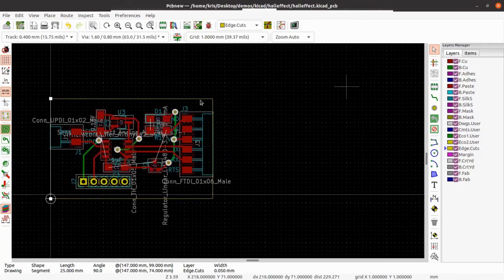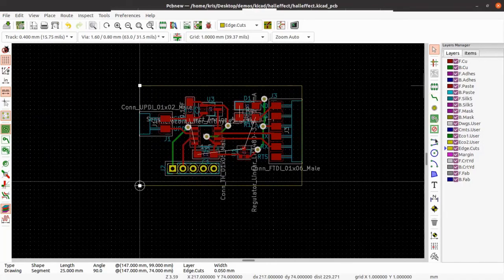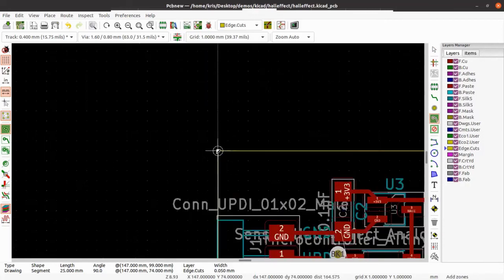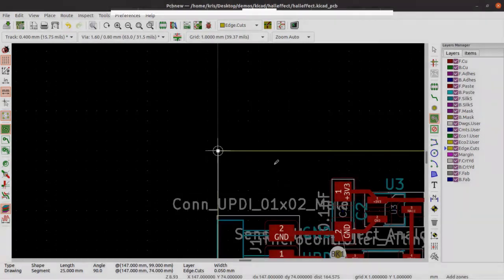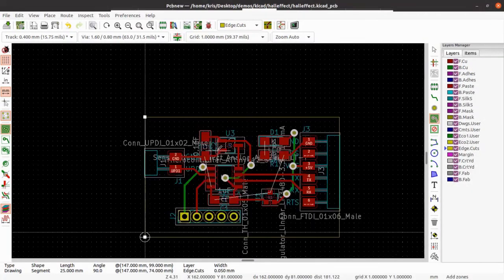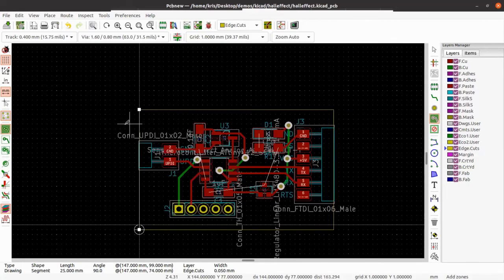And then on top of that, I'm also going to do a copper fill, copper pour, and with the double-sided board, what you can do is a copper fill on the other side of the board. So you can use the bottom side of the board as the ground layer.